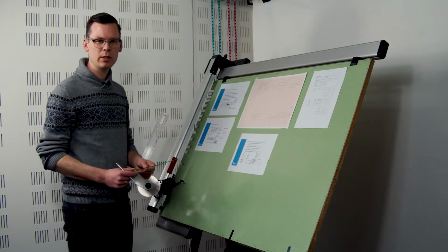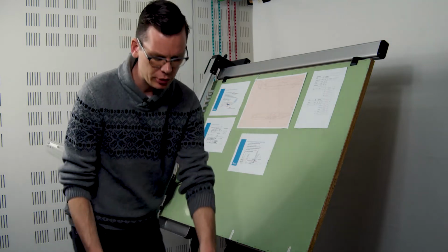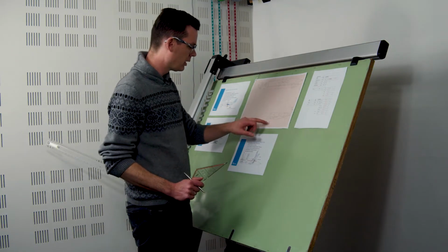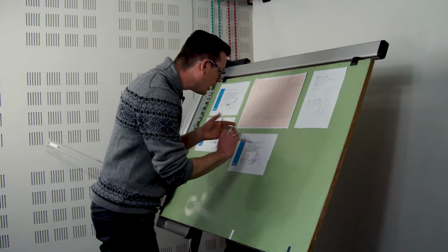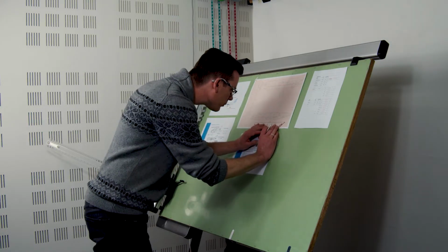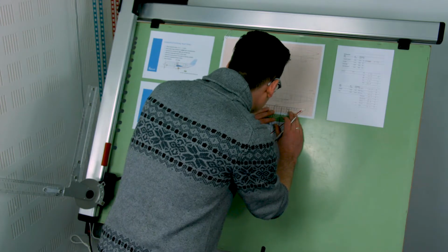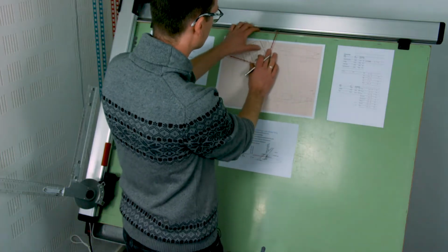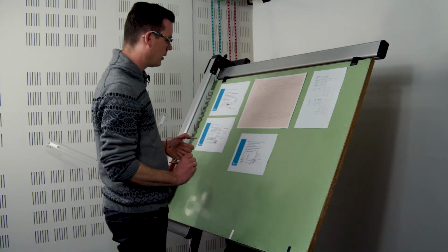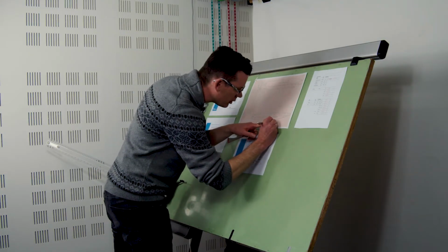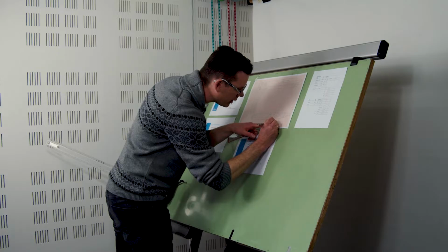And that is something that we can now actually measure in our drawing, because we have the most aft CG position and we have the axle, and the distance between that is exactly 90 centimeters. So this Lm, I'm writing it here, Lm equals 0.90.